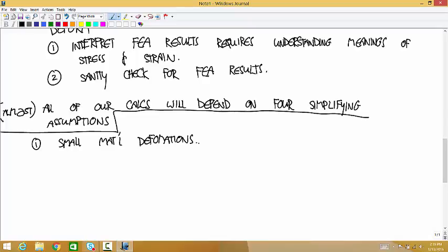That's the biggest that it's going to be. If you imagine a steel bar in an engineering application and you put a big force on it, you can apply a pretty big force to a steel bar before it deforms 1/10 of a percent. It's not stretching or contracting very much.